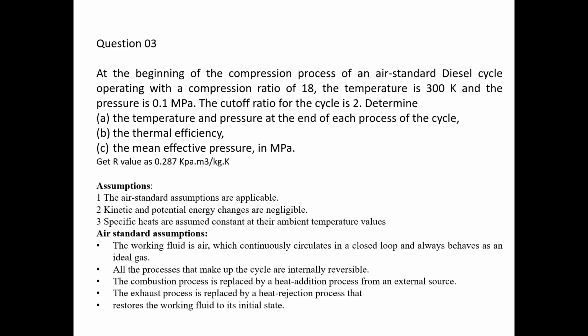So the assumptions are that the air standard assumptions are applicable. Below you can read those out. Then the next assumption, kinetic and potential energy changes are negligible. Specific heats are assumed constant at their ambient temperature value. These are the assumptions we normally refer to when working this kind of example. Now let's work on the example.